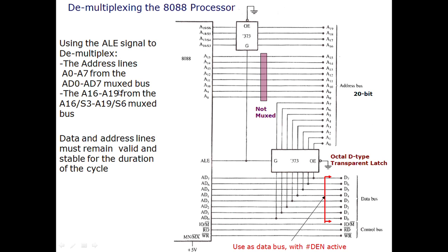So it enables the latches to separate the addresses. So these two latches would allow the addresses available at these inputs to be given as output whenever the address latch enable is high, and exactly that is the time when the microprocessor is sending the address on these multiplexed pins.